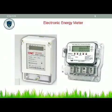Electronic energy meter. Electronic meter measures energy using highly integrated components. These are very accurate and reliable types of measuring instrument as compared to conventional mechanical meters. It consumes less power and starts measuring instantaneously when connected to load. These meters might be analog or digital. In analog meters, power is converted to proportional frequency or pulse rate.